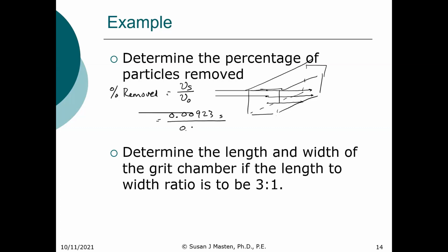And we divide by the overflow rate. That is equal to 0.554. So roughly 55% of these particles are removed. If this were an upflow clarifier, what percentage of these particles would be removed?